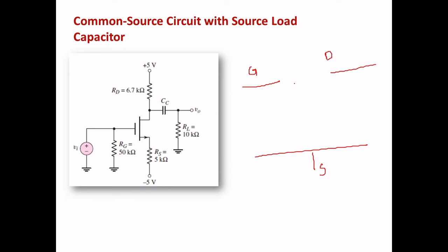Okay, so first you have a mathematical modeling VGS. Here below the source you have a resistance, so that has to be represented RS. Here you have a dependent current source, gm times VGS. That's all. Then this R0 I am not including, early effect not including. So this part is completed. Now see, I am adding this RG.